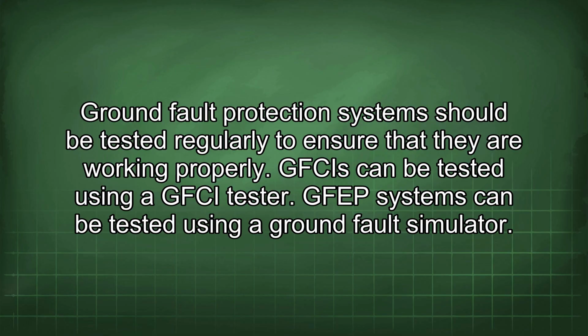Ground fault protection systems should be tested regularly to ensure that they are working properly. GFCIs can be tested using a GFCI tester. GFEP systems can be tested using a ground fault simulator.